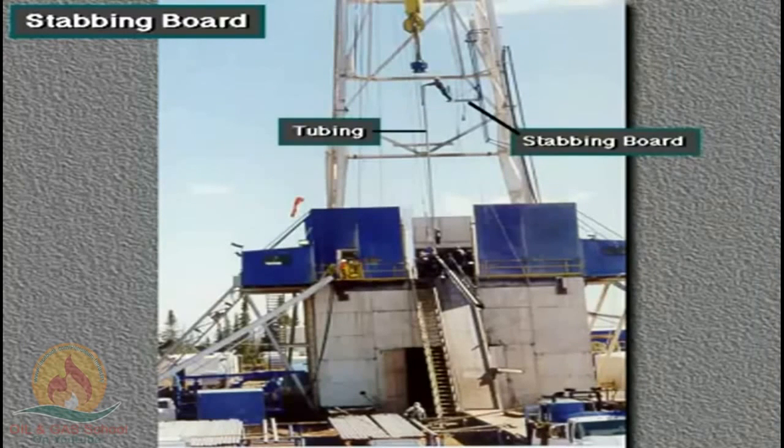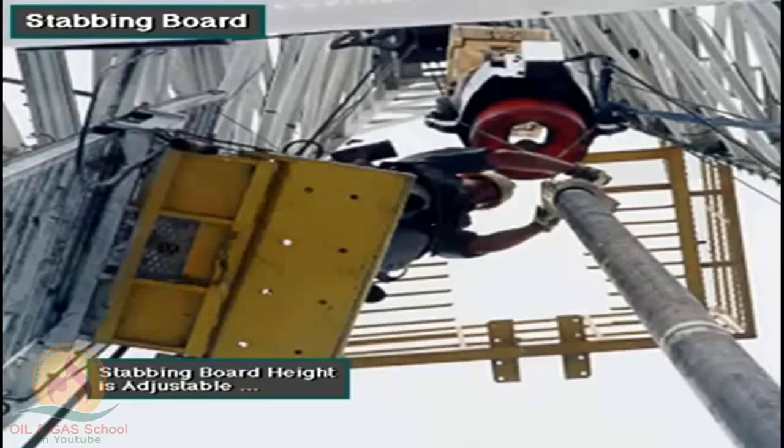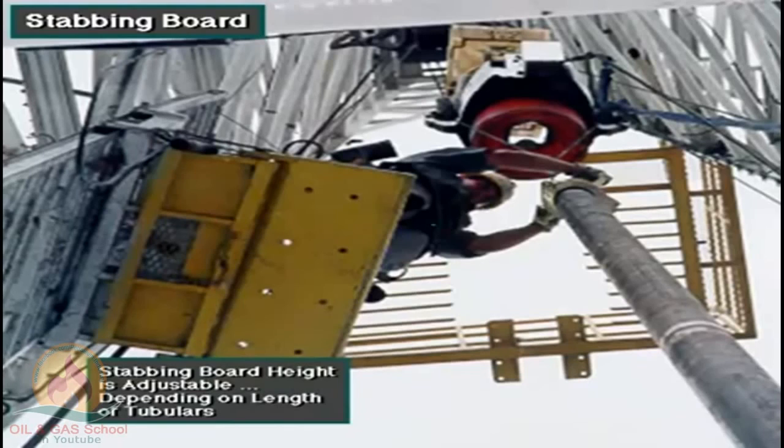The derrickman guides the top of the casing or tubing from the stabbing board. The crew member called the stabber adjusts the stabbing board's height with a hydraulic, electric, or air-powered motor. The height varies depending on the length of the casing or tubing being made up and run into the hole.